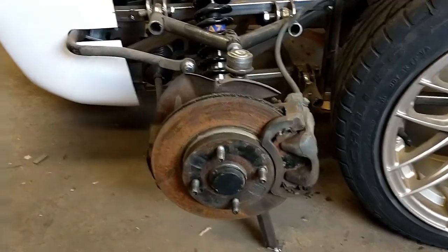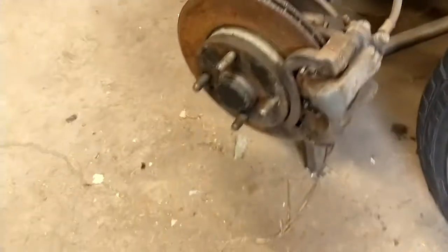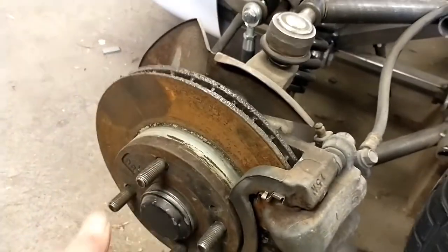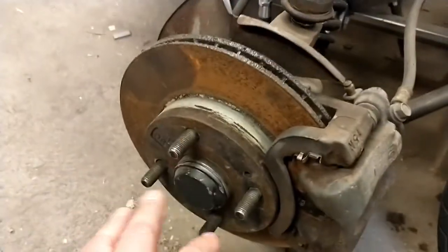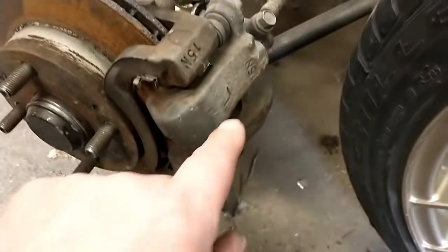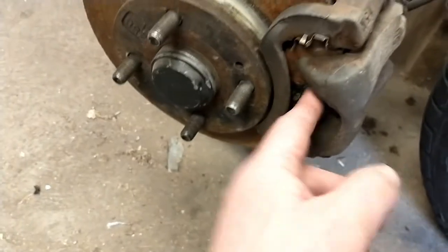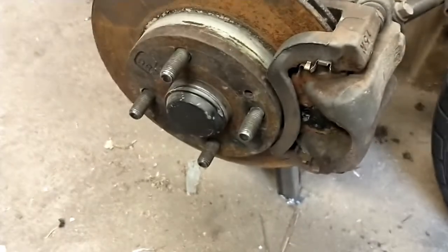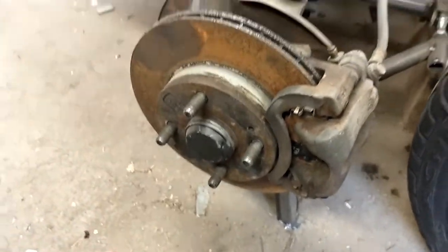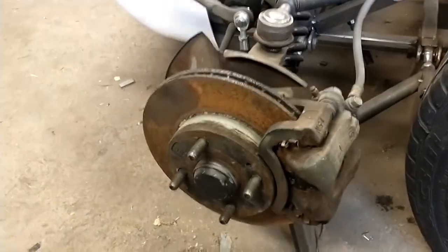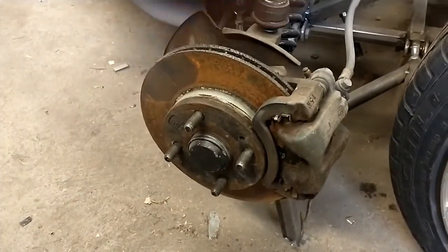Of course, as for how brakes work, just quickly: there's the rotor, which is attached to the wheel through these lug nuts, and there's a piston in here which is driven by fluid to clamp the brake pads against a disc. This friction stops the disc from turning, and that is transferred to the wheel, which stops the wheel from turning. That's the chain that has to happen for the car to stop, and that's what we'll be examining a little more closely.